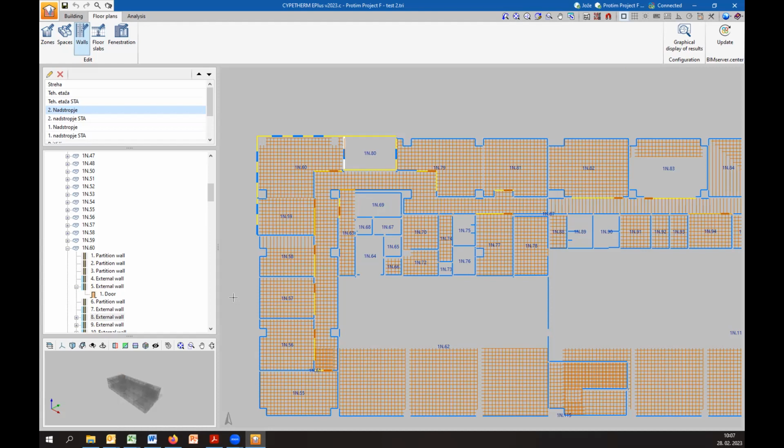It's strange. I have to admit, it's strange. Maybe it's because of the type of column you have used. Generally, I don't know. We used structural columns. We always use structural columns. You have another layer over the columns, right? Is it a separate layer, or is it a part of the column? No, it's not a part of the column. I think we have a finishing. Yeah, I think that's why, because then it's like another wall, and then it recognizes it as a wall.